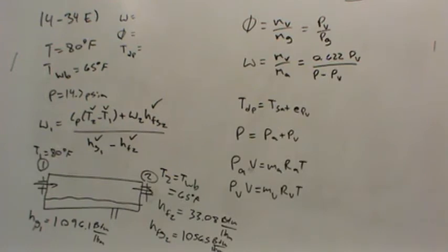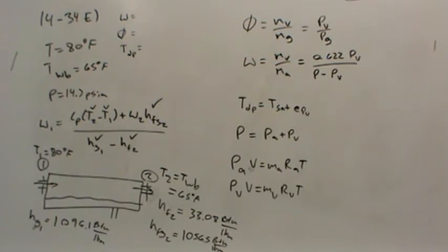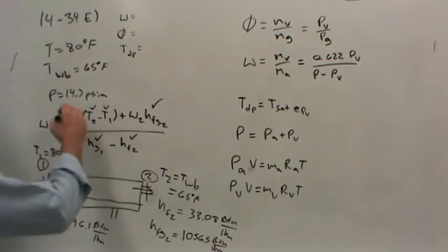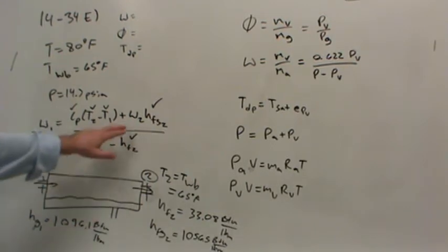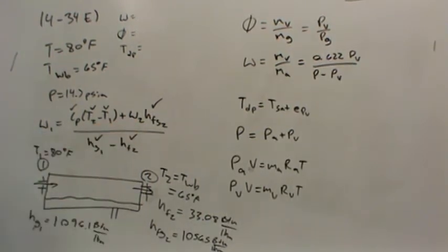Anyway, since you didn't know that, go to the back of chapter 14 where the equation is given. You may want to make yourself a note on page 754, the lower left-hand corner of the page, that the Cp in that equation is for air. Okay, that's the heat capacity of air. So looking that up is no big deal. It's 1.005. What about the absolute humidity at state 2?